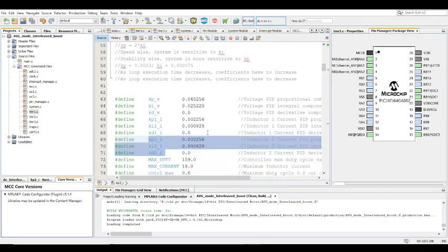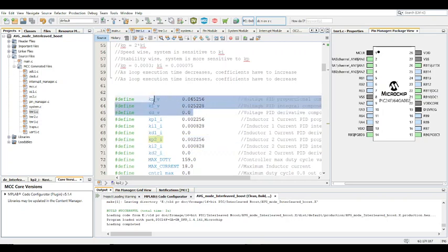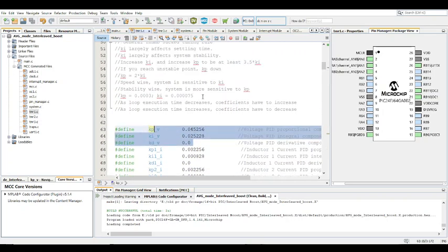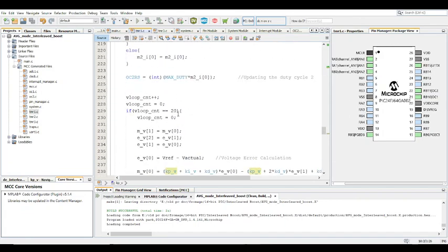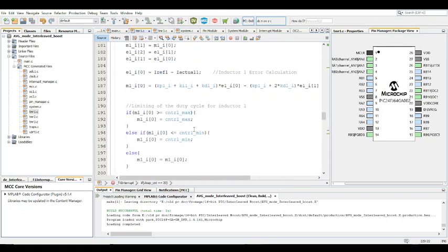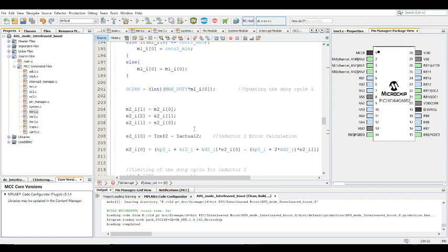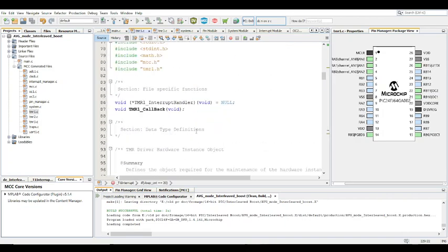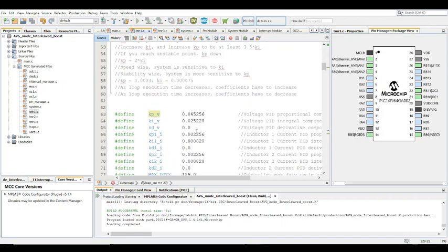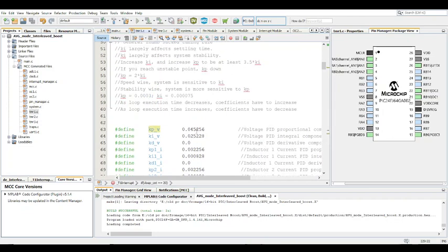So after you do that and make sure that it gets to the set point for the inner loop, then you're good to go. Then you can add the outer loop. And when you add the outer loop, you want to go gradually. You don't want to make the inner loop unstable with the outer loop. Also with regards to the speed of the outer loop, this value here, you could change that to 10, but do not go below 10 because it will make the inner loop unstable. You basically don't give it enough time to get to the set point, because it's too quick. It's better to have it above 10, essentially what I'm trying to say.